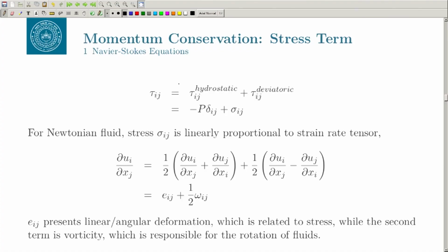Now, if the fluid element is at rest, then also some stress is acting on it, some force is acting on it. And what is that force? It is the pressure force, right. You can have pressure acting from the normal direction everywhere. So, it will be part of the normal stress, right. So, the pressure is acting on this if the fluid is in a static state. So, this force is called the hydrostatic force or hydrostatic stress. Force per unit area is called the stress, right.